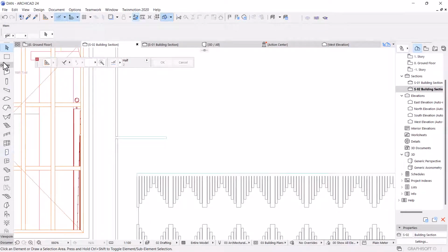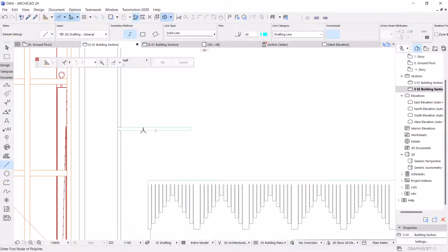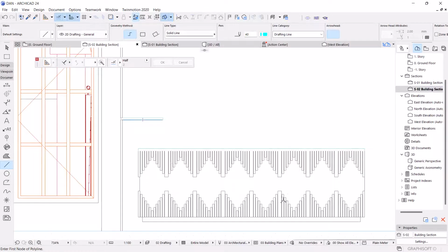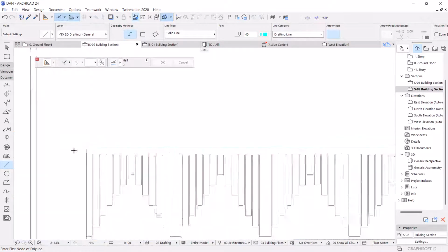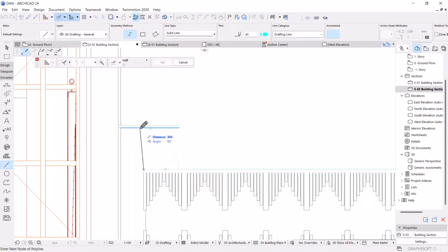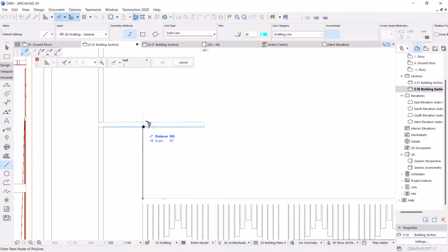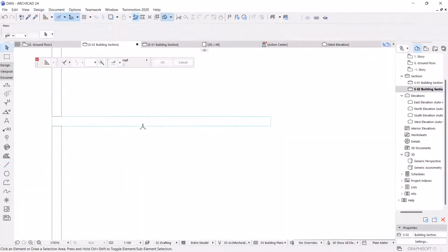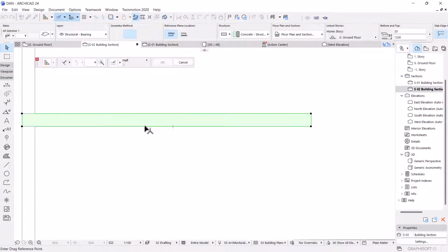So this is the section, and at this point I just want to confirm the height of this slab that I drew from the top surface of the other slab that we drew for this unit. I don't know the name to give it, TV stand or whatever. So I want it to be 300 mm from the ground, which I did 305, but I want it exactly 300. So I'm going to drag it downwards by 5 mm.